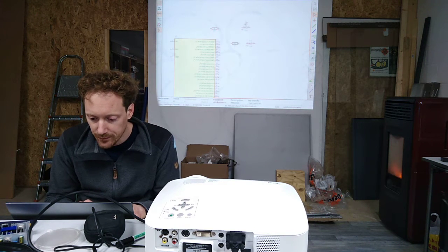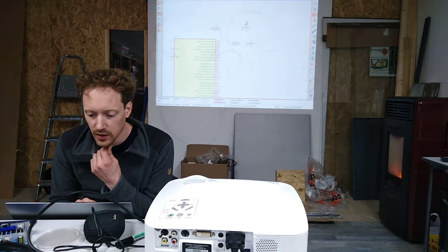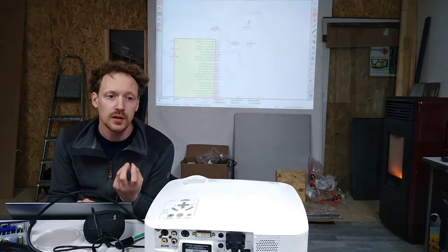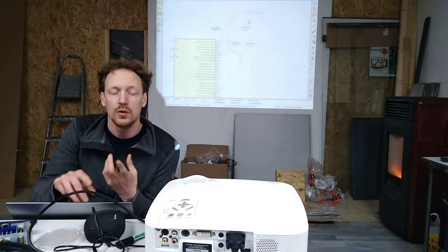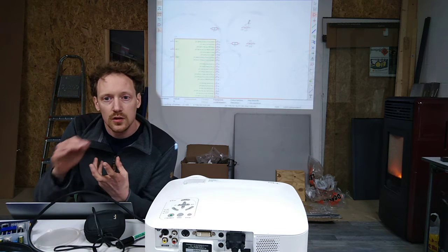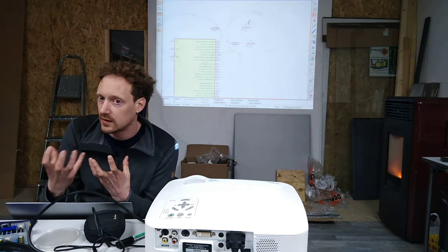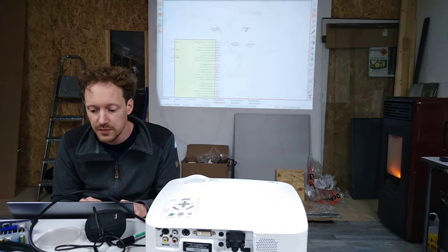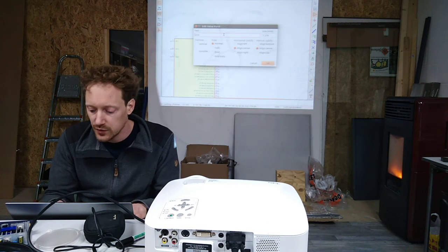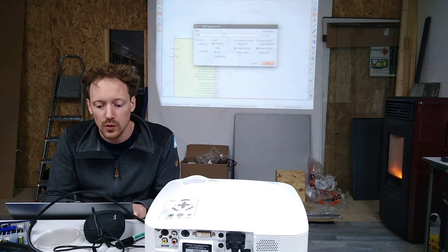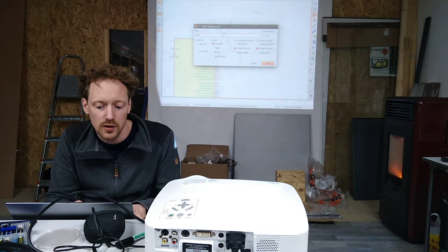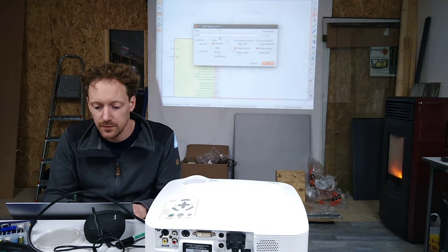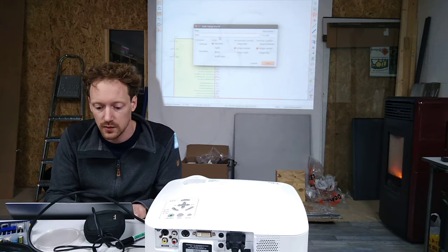So you can see here that there are reference names for each component. It says D question mark, and the system will number each component to let each component have a unique name. But we're going to do that a little bit later. So if you press V here, we have some text, LED, and we can give it a nice name, red LED, for example. We can do the same for this one as well, red LED.